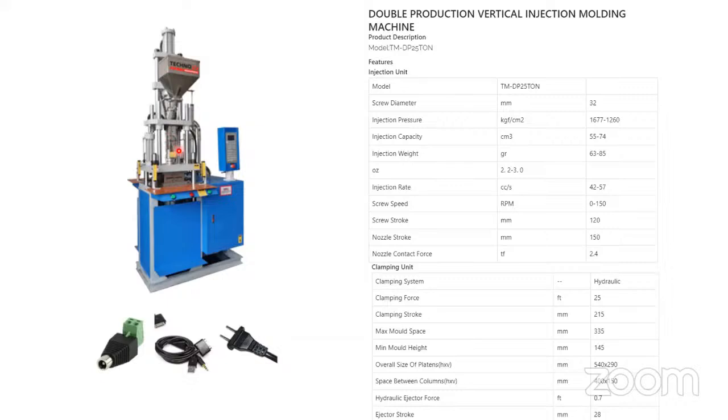And inside the barrel, there is a piston or maybe a screw. Now, friend, this is a movable platen attached to a core plate. This is again a cavity plate. This is a complete panel. We can move it up and down. All the functions can be done by this. Even manual and semi-manual are possible in this case.